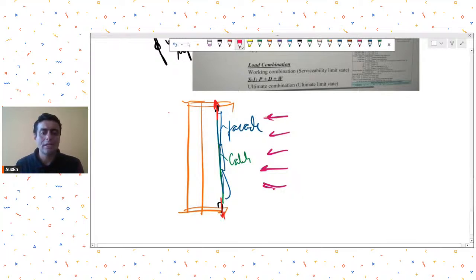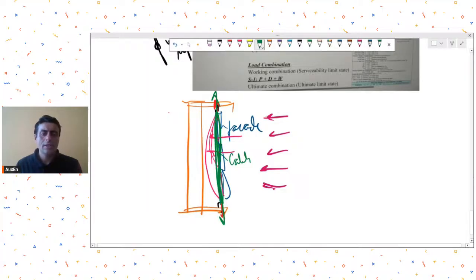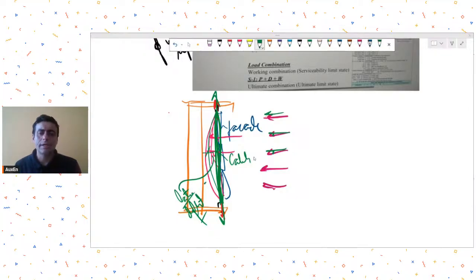Because otherwise, this cable will not be able to hold its position, and if it's not able to hold its position, it will not give you the required lateral resistance. Are you getting it? So, to get the lateral resistance required, you will have to pre-tension the cable so that it maintains a certain tightness, and then when designed for lateral load, it's able to maintain its deflection value.